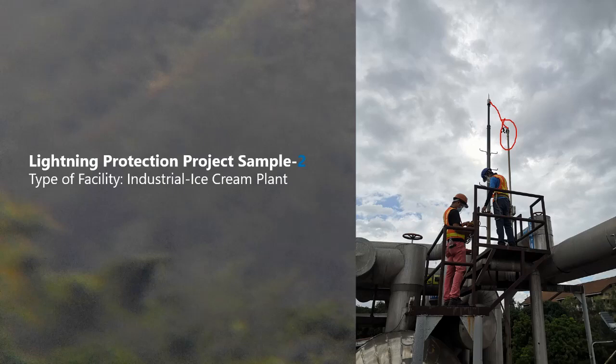As an engineer, I will not allow this kind of design near the lightning protection system, even though the code gives us a minimum distance of at least 250 mm. I think it's 250 mm, the allowable distance for the air terminal. I'm not 100% sure, but you could check, but I think it ranges from that.